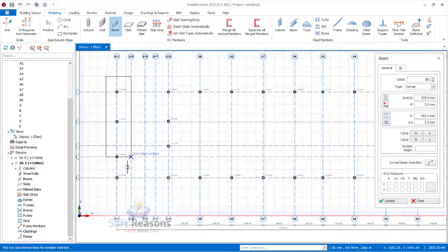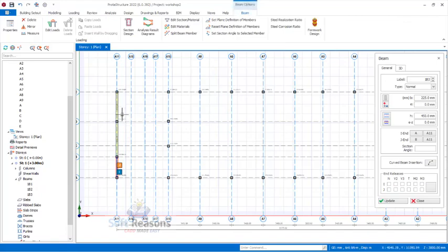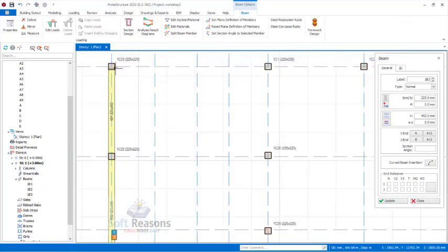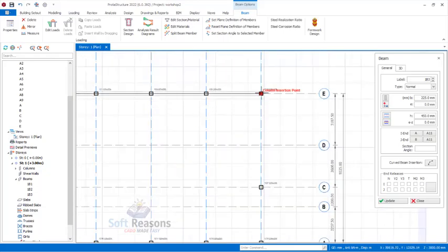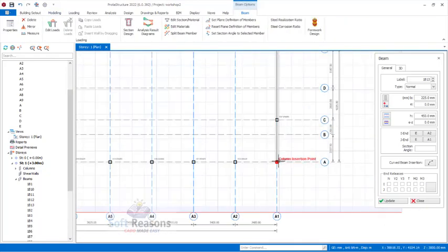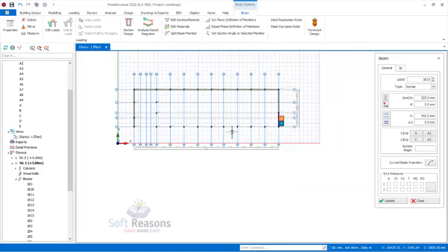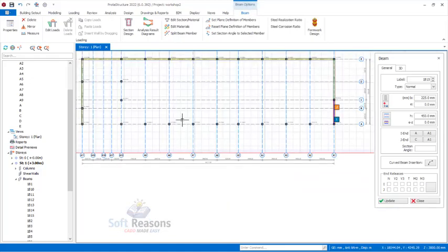So you can do a window over a particular provision to have it placed successfully. There are various ways of drawing beam members. So this is the first method. Okay, so you can now pick the first column, take it all the way to the last one, and pick also to have it placed just like that. Okay, so you can right click to get rid of the command.